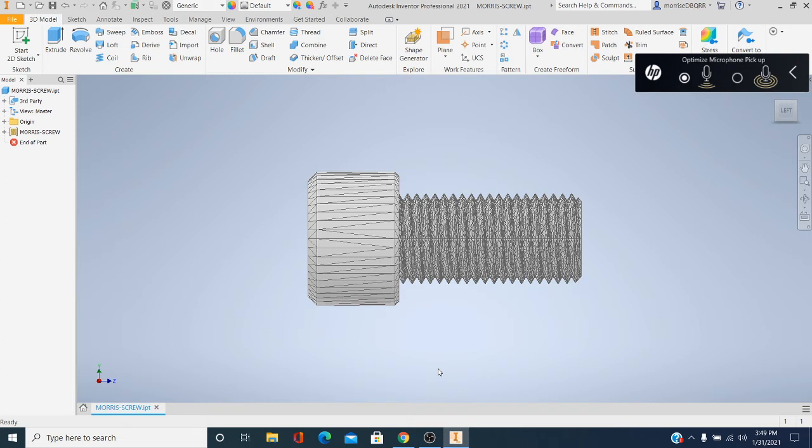When you go into Inventor, you're going to open up the IGES file. And like I did in this video, I converted the IGES file to an IPT file, Inventor part file. And then you should probably save it as an IPT. Once you get an IPT, you can then open that file back up, or it might still be open, and you can save as an STL file.